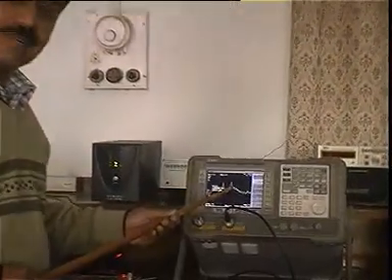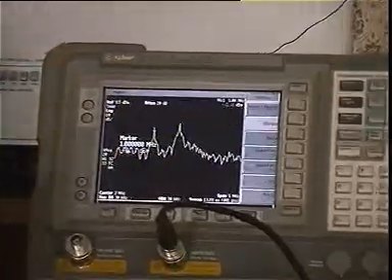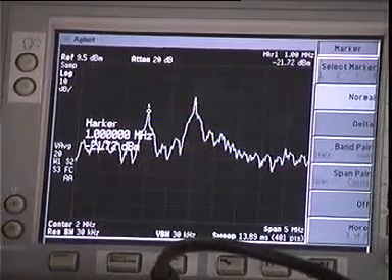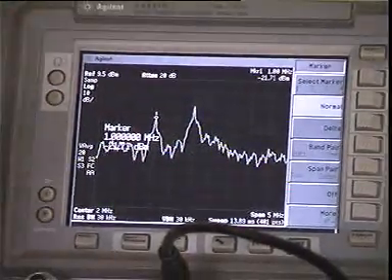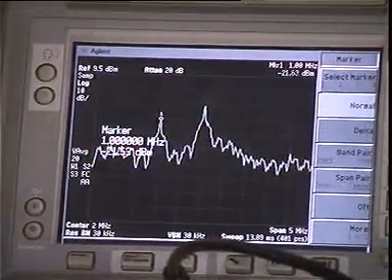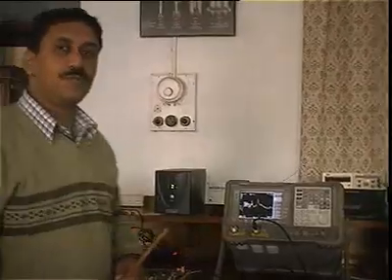This is a 2 MHz peak transmitting one of the bits, this is a 1 MHz peak transmitting the other bit. Okay, so this is how the FSK spectrum should look like. The basic nature of the spectrum will still be sinc square, except that there are two carrier frequencies here, so the sinc square spectrum will be centered around two carrier frequencies. If I were having more symbols to transmit, I will have more peaks. Each of those peaks will be a sinc square spectrum centered around that particular carrier frequency. Okay, so this should be clearly understood by you all, and this is very beautifully shown on the spectrum analyzer. Next, let us go to phase shift keying.